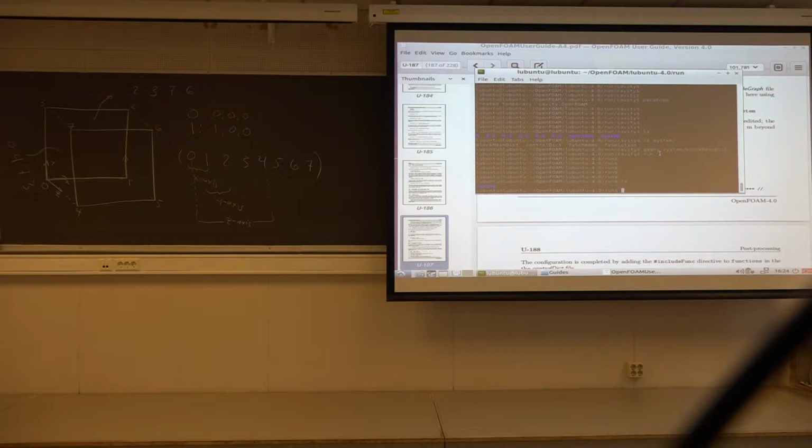So I start by copying the pitzDaily. That was under OpenFOAM, tutorials, incompressible, and then it was simpleFoam. And here I think it was pitzDaily.